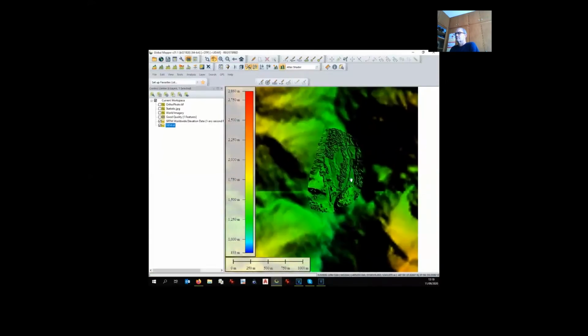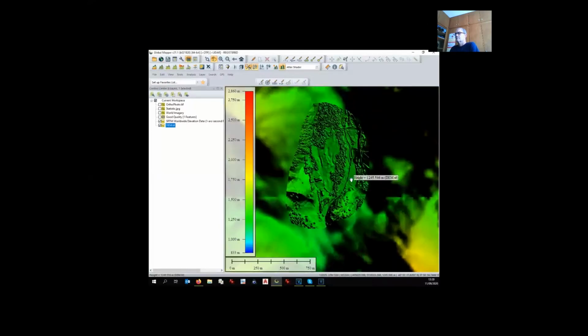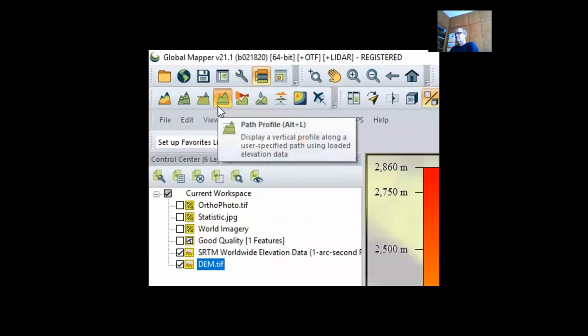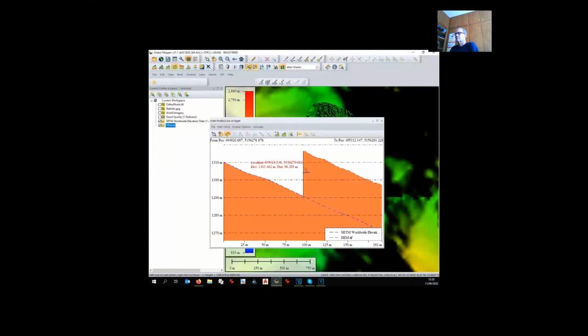It is very difficult to judge the quality of the two models, but you can see how precise the elevation model done by the drone is compared to the elevation model of the internet. But now I would like to show you something interesting. If we take the profile from here to here, we see a big step. We have our drone model, the red line, and the free digital elevation model, the blue line, and in between we have almost 25 meters.